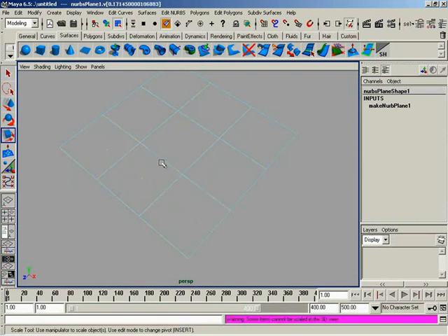Look at that. Now, what does this give us? It's an isoparm. I like to refer to it as an isoparm marker, allowing us to denote a very precise location on this NURBS surface where we can tell Maya tools to perform operations. Remember, we had the curve point back over on NURBS curves where I was able to mark out a specific location on my curve and say, chop it right there. The same thing works here.